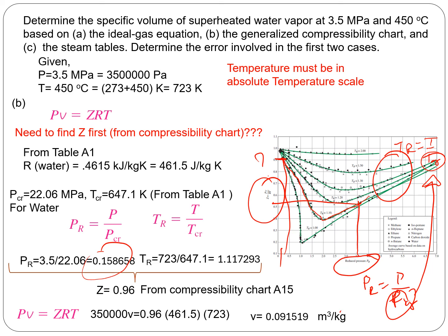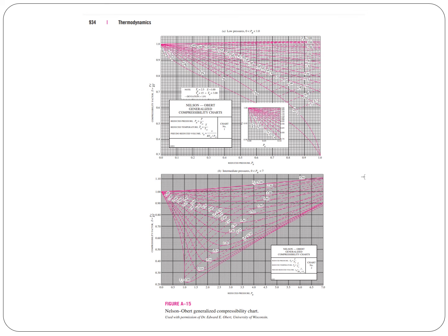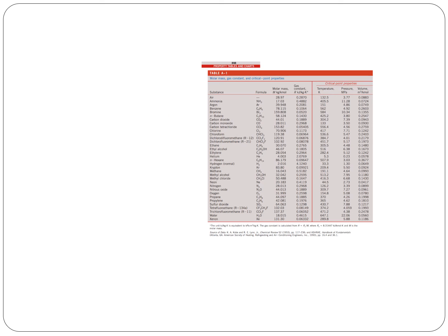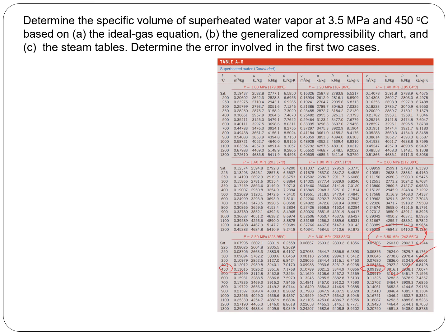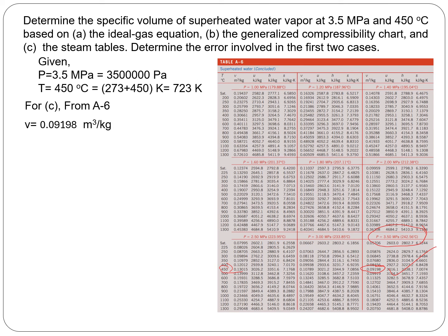Again, sometimes like in the open book exam problem, it could relate to the specific volume as well. Okay, so if that is the case, you have to make use of these charts. These dotted lines here are for the volumes. So I think that's it.